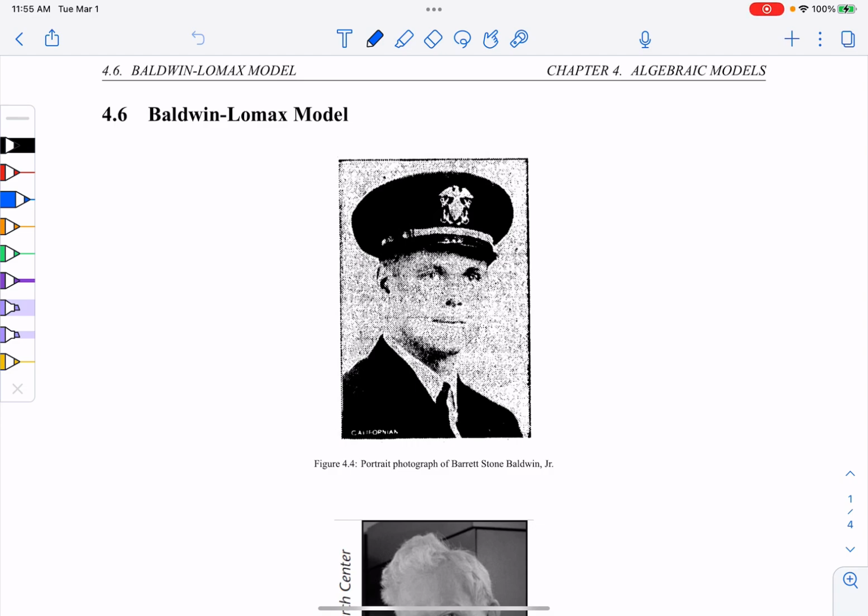So as I first mentioned, we'll first look at the Baldwin-Lomax model. And I should also mention, if I haven't already, that this is the model we will program in your last computer project. So in the present computer project, you're trying to get your laminar flow solver running correctly. And you'll see why this model was so popular, because you could just take an existing Navier-Stokes CFD code and add in a viscosity term and a few ways to estimate the viscosity through a two-layer model and have a fully functional turbulent flow solver, which was used in practice.